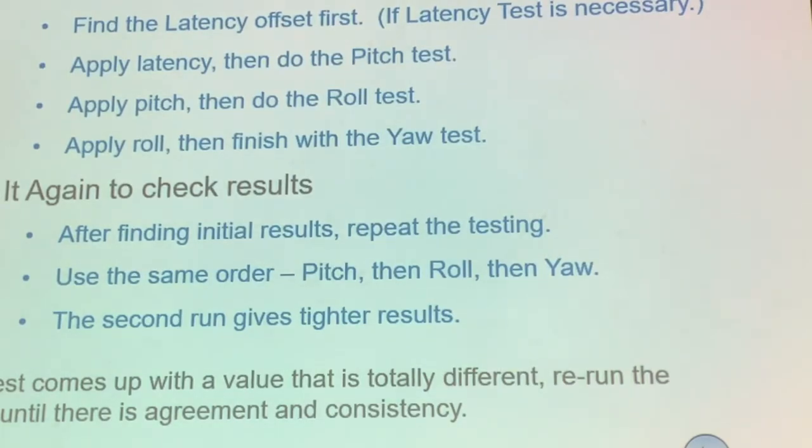Normally when you're doing the patch test, the first one you should do is latency, for GPS. After that, in some cases people do pitch first, but normally I advise you to do roll first. After the roll, do the pitch, and then the yaw. Then after that you check again to make sure all the values are okay.